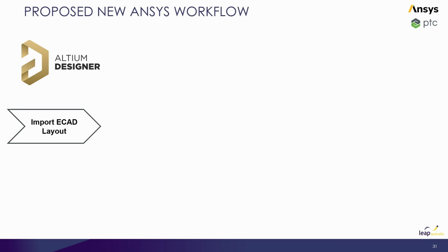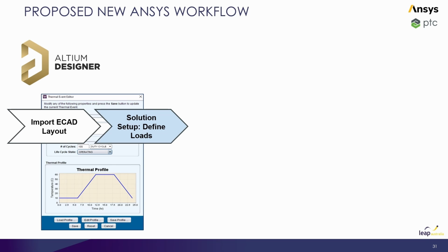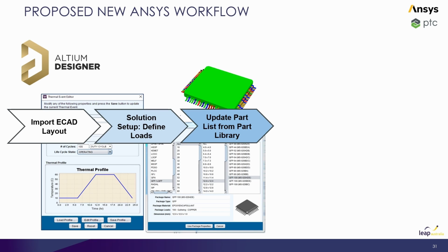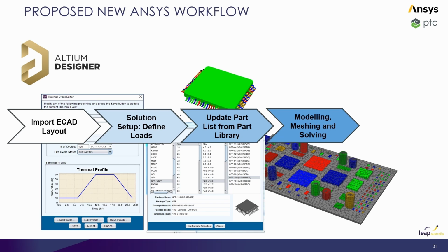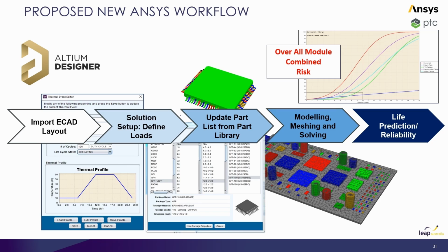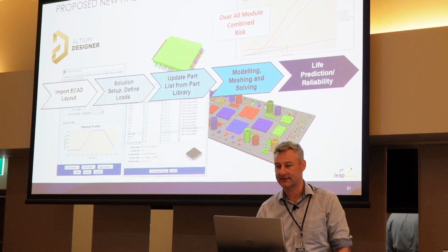And how that works is you bring in your Altium design, in this case, it's an ODB. You apply your loads. The Altium PCB will be understood by the engine, but the components, the mass and the leads are coming from our library that then is placed on top because, of course, for vibrational analysis, the mass of the component is super important. And then the software will quickly form a mesh and then calculate the curve for you based on different design rules, but also JEDEC standards and so on.